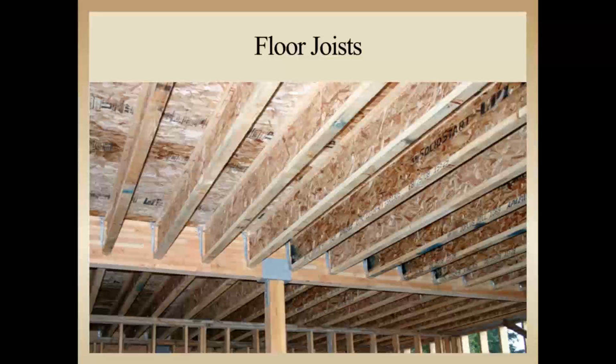Here, I-joists are being used as repetitive floor joist members. Note that in the foreground, the I-joists are hanging from an engineered Glulam beam supported by a Glulam column. The I-joists in the background are used as floor joists in a continuous span over an intermediate bearing wall.